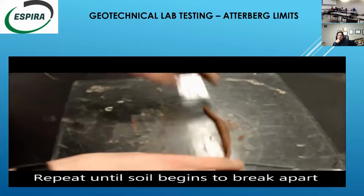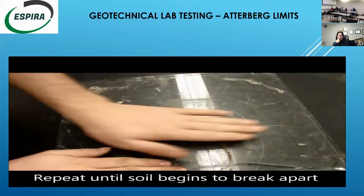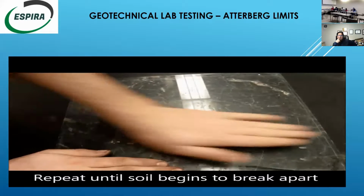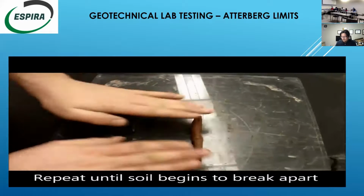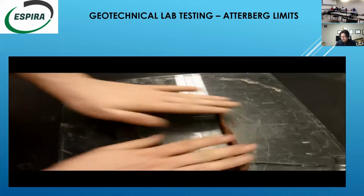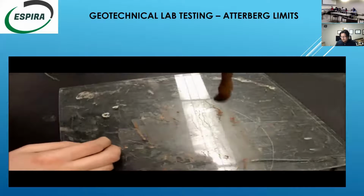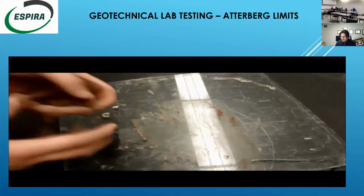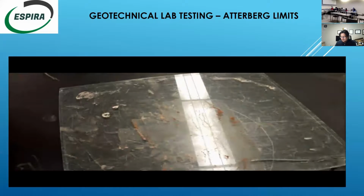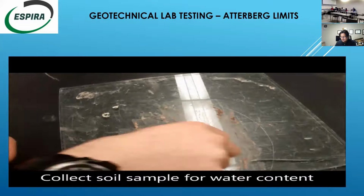This mixture is then rolled on a glass plate using one's palm until the soil is about 1/8 of an inch in diameter. The soil is then rolled up into a ball, and the process is repeated until the soil begins to crumble before becoming a thread. The soil is then placed in the tare and is massed and dried in an oven of no more than 140 degrees Fahrenheit, and then massed again to determine the water content of the soil at the plastic limit.